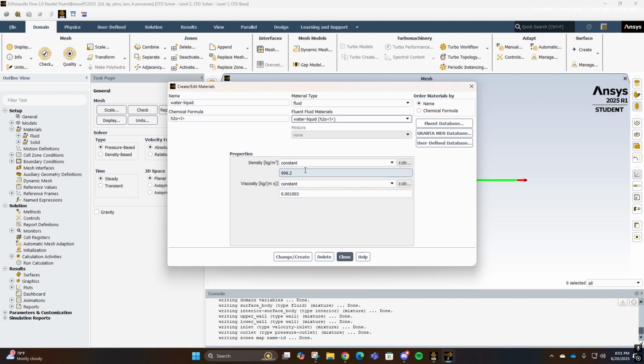And as you can see, our density is, we're just going to keep it what it gives us in the viscosity. It's around, if you look up online, the density temperature tables of water. This is about the temperature and dynamic viscosity at somewhere between 20 and 25 Celsius. The density is around 1,000 kilogram per meter cubed, but we'll keep it at this and this viscosity.